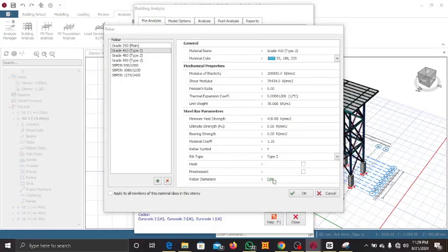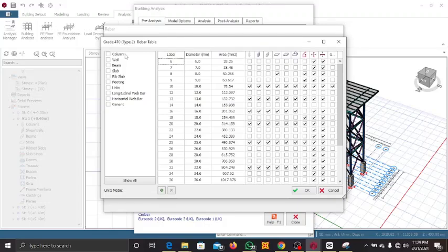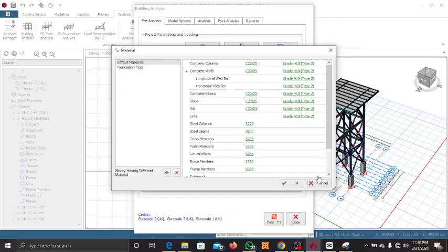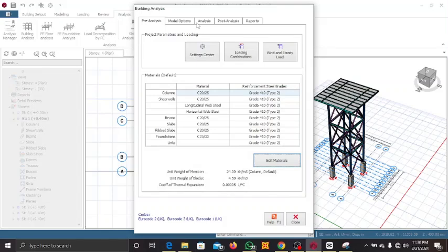you click on edit. Okay, so for our rebar diameter, for the first column here is the column, we want it to provide Y16, only Y16. So we are going to untick every other thing in that column and just leave a tick at Y16, since that's the only concrete member we are going to be having on this model and design, so we can forget about this other side. Click OK. OK and OK. So you come to your analysis.